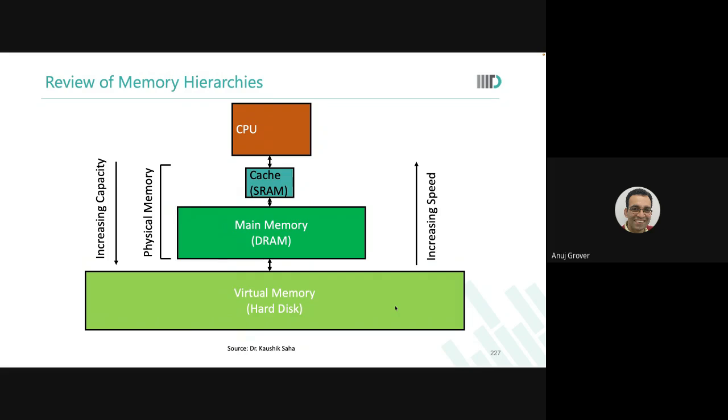See, in memories also, if you scale from one technology to another, the target for the technology team is that the memory area should go to half. But to be able to take it to go to half, you also have to handle these PR ratios and CR ratios. You have to handle stability, writability, so many things. That was why I asked how many of you started work on your projects. So if you started work on your projects, you know what a pain it is to just design even in 65 nanometer. To handle that, okay, stability should be there, performance should be there, this should be there, that should be there, all those things, it's just a nightmare to design.